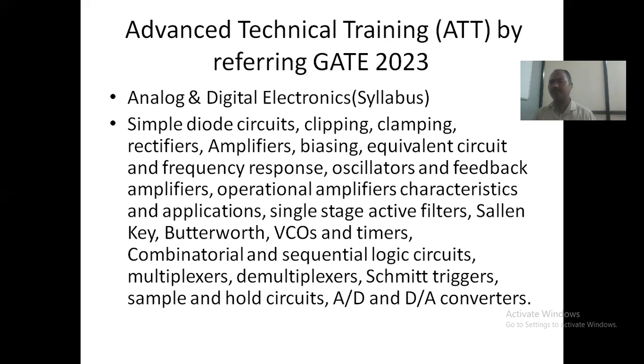See, there are two types of full wave rectifier: the full wave bridge type rectifier and the full wave center tap type rectifier. In these rectifiers, a transformer is used, right? We know that bridge type and center tap type use different types of transformer. The center tap type has a three wire transformer, meaning two wires for the input and three for the output. The center tap is used in the center tap rectifier. In the case of the bridge, the normal two wires at input and two wires at output are used. These are the two types, the center tap and bridge type rectifier.